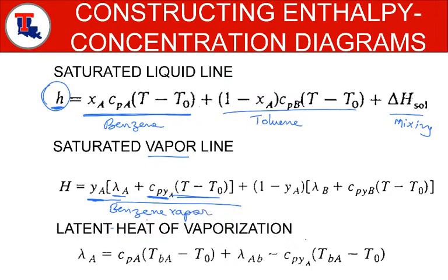And this second term here is the enthalpy of toluene in vapor. Typically, the heat of mixing of gases is minimal, I shouldn't say zero, but minimal. You'll never see that reported. Usually it's the mixing of the liquids, because molecular collisions are higher in the liquid phase, whereas in gas phase molecular collisions are less dense, right?